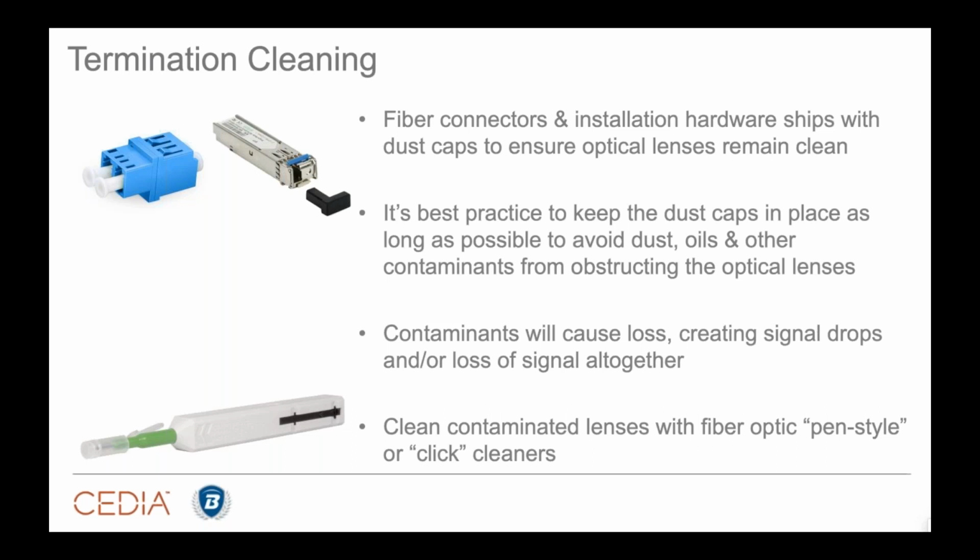Let's think about this. Optical cable is sending light waves. We are sending lasers through a glass or polymer pipe out through lenses into electronics that will read those light waves. If we have dirty connections, those lasers aren't going to fire cleanly. You're going to have loss, okay?